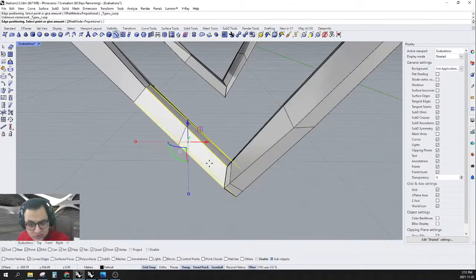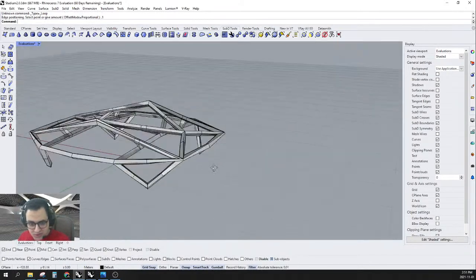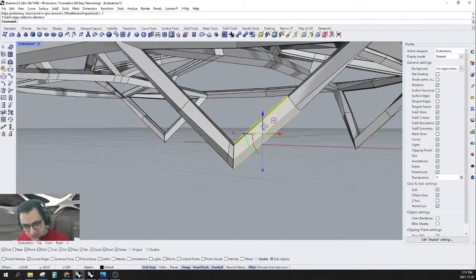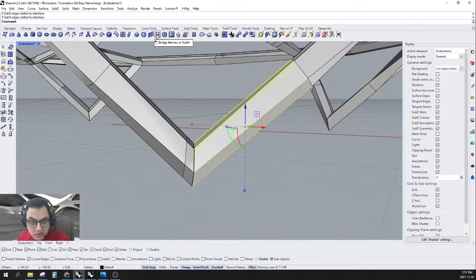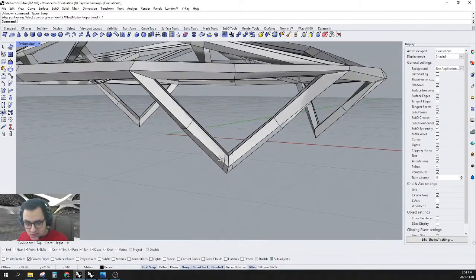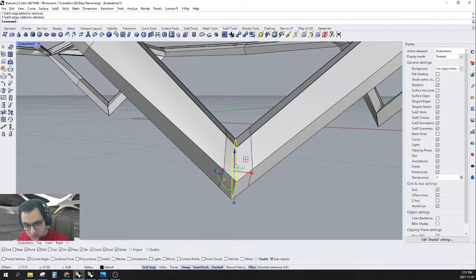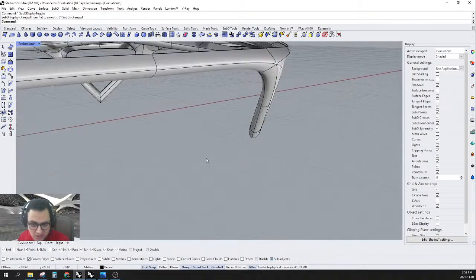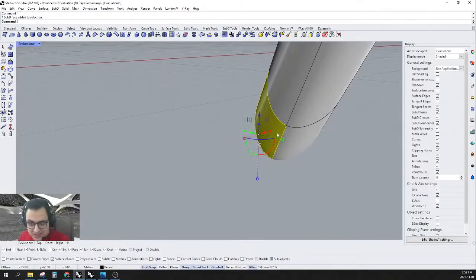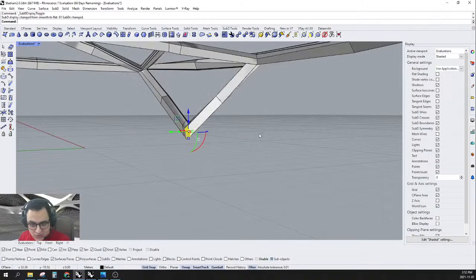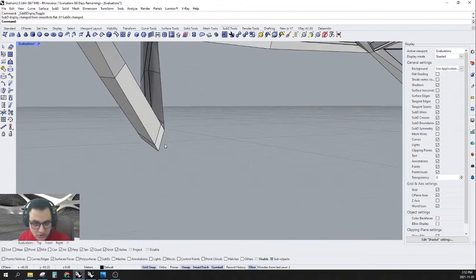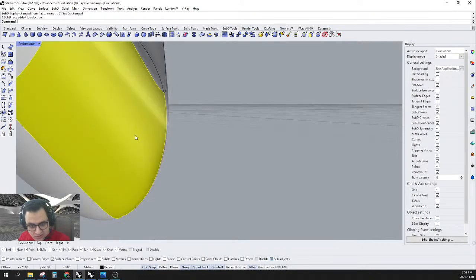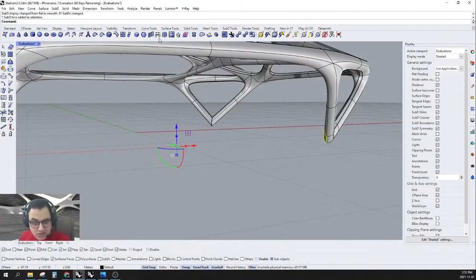Okay, and use it again, 0.1, perfect, and do this again, select it, and okay, insert 0.1, perfect. After that, I don't want these. Double click and double click. I don't want these to be creased, so I will remove the crease, and now I will have something like this. I will simply select this face in here, which I created now from this one, and I will select this one as well and simply bridge it.